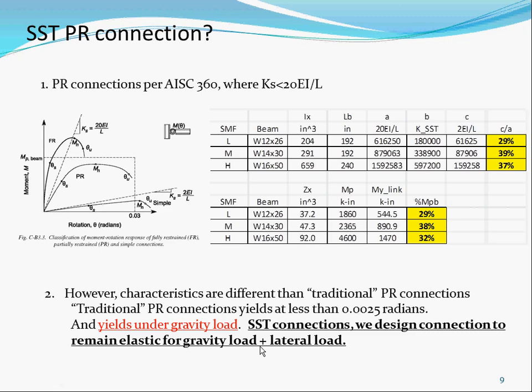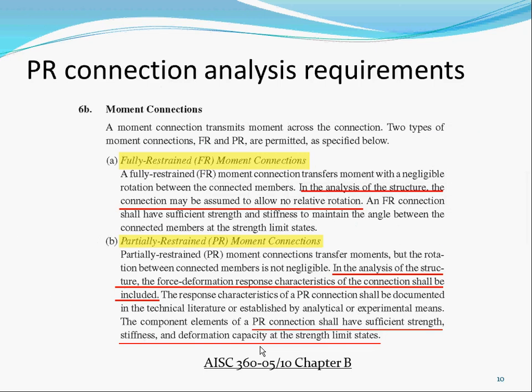We're gonna do all the load combinations, and then earthquake plus dead plus live. We're gonna come up with a moment, that's the demand, and then we're gonna size the link for that demand. So which means we're gonna be in the elastic range. So we don't yield under those loads. We only yield under like a big earthquake. But remember, we're talking about all the designs in the U.S. are pretty much in the elastic range. So that's the same concept we're gonna take when we do a design later. But this is just a background of what we are.